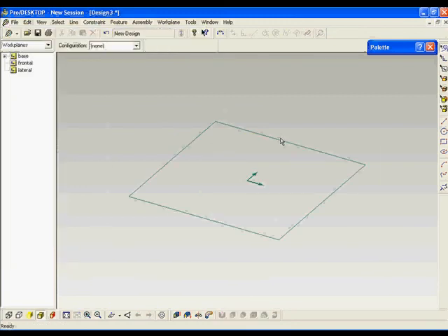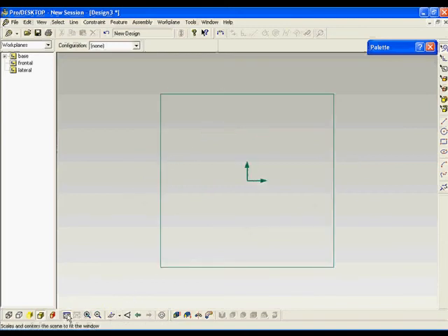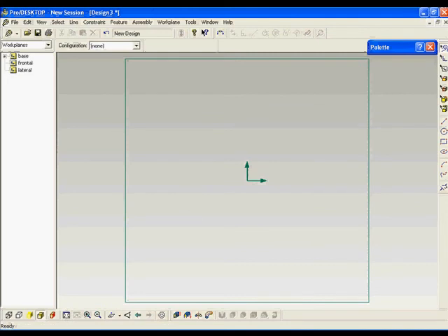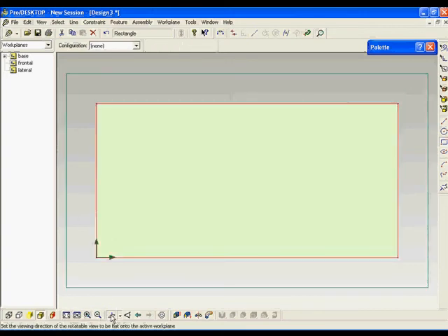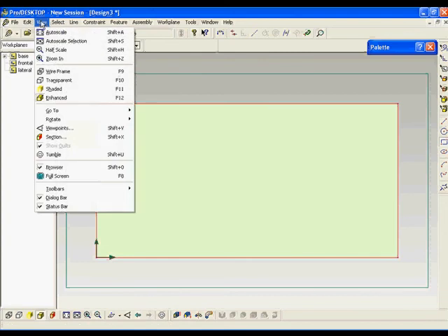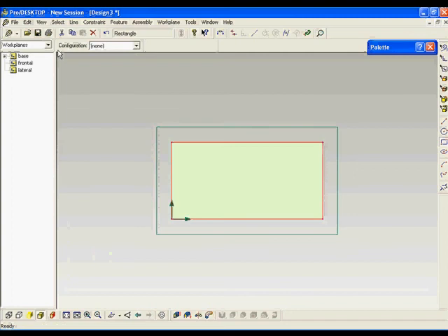We'll go into File, New Design to create the van body itself. Rotate the workspace so we have a straight viewing of the workspace. This time we're going to create a rectangle starting at 0, 0, moving into quadrant 1. We are then going to auto scale the view and go in. We're going to redimension the top edge and the right edge of this rectangle so it becomes 24 inches wide in the X direction and 12 inches high in the Y direction.